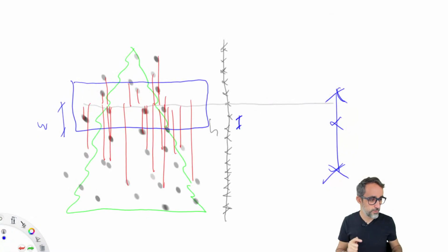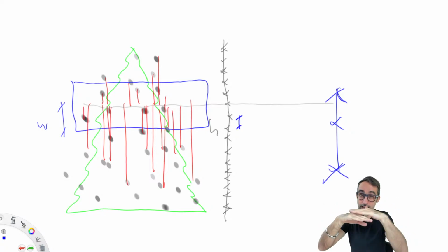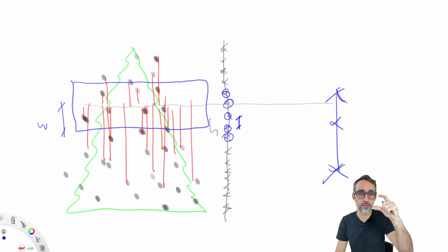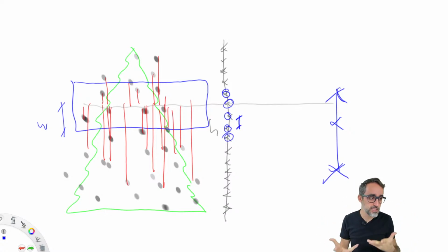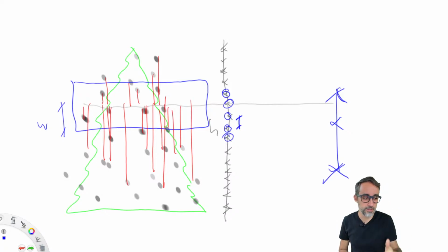In the diagram that we used to explain this, we were talking about a horizontal plane. So we might be tempted to actually use a plane object inside of Grasshopper. But because this scenario is very simple, it's just a horizontal plane, and a horizontal plane always has the same z height. So we don't actually need to work with an actual plane so long as we know the z height for each frame. We can just use that z value and subtract it from the z coordinate of each one of the points, to find the distance between this virtual plane and each one of the LED light points. If we were working with an inclined plane, maybe using an actual plane would make things easier, but because we're working with a straight horizontal plane, working with the z values right away will make things easier.